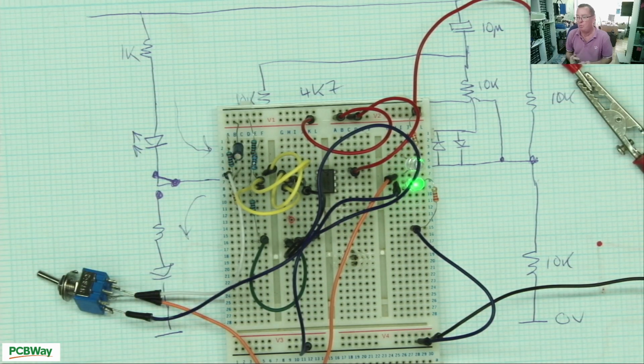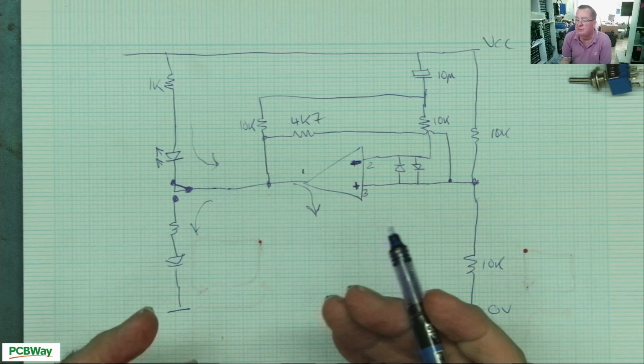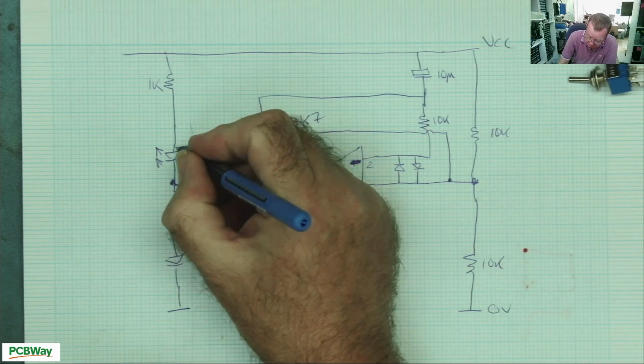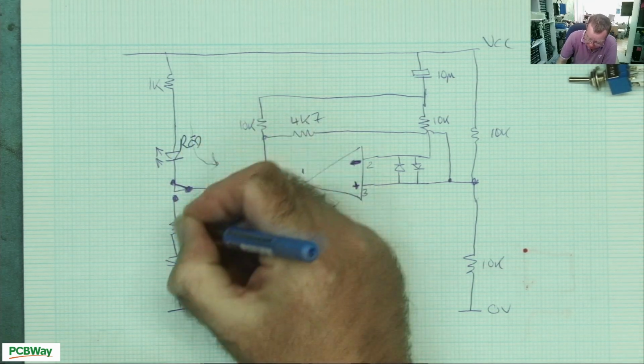And as long as you know what is going to happen with a particular chip, and the datasheet will tell you if it's open collector or not, I think that is probably the best way to go, because it's possible, as I say, to have a fault where it can only sink or only source current. But what do you guys think? And what do you think about that? For me, I'm going to include this on the PCB, and then, to be quite honest, anybody building this, you have the choice to include it or not. Okay? So for those of you who actually want to build this on Vero board now, this was the red LED, this was the green LED.